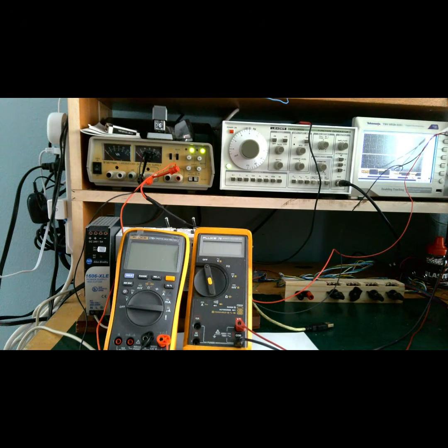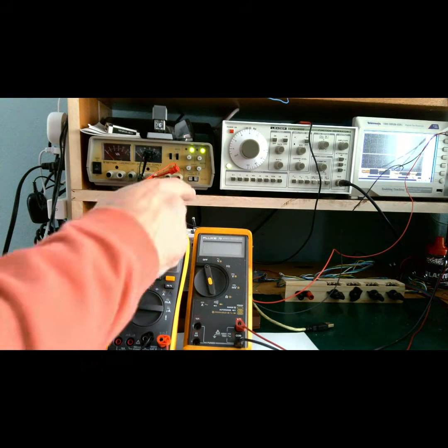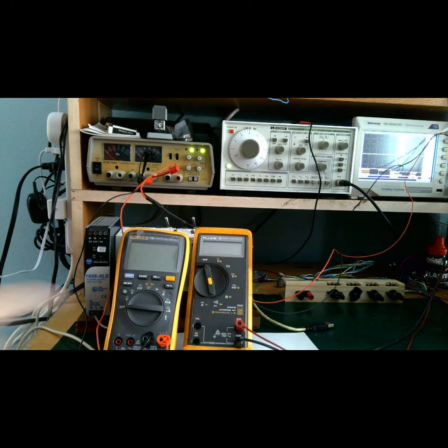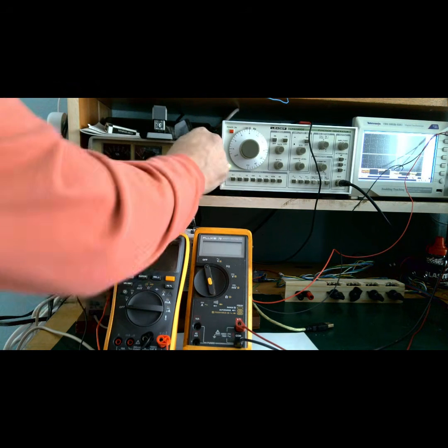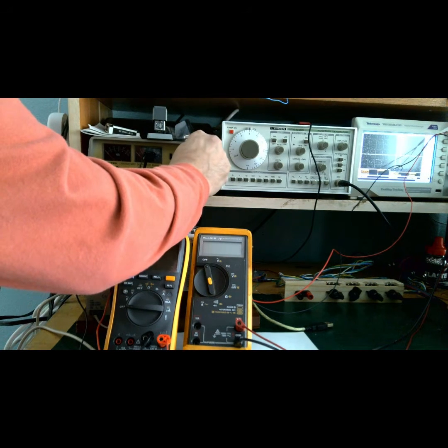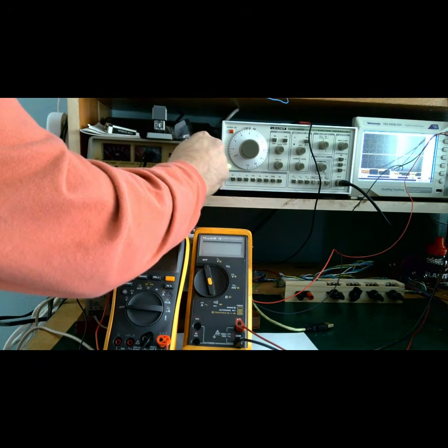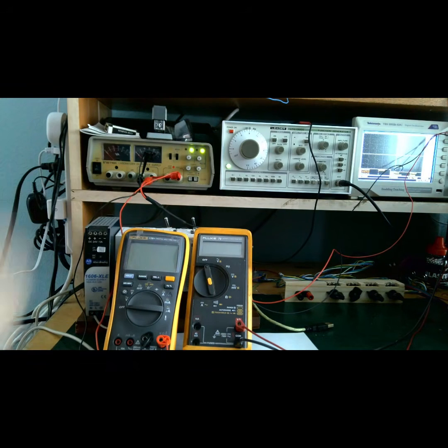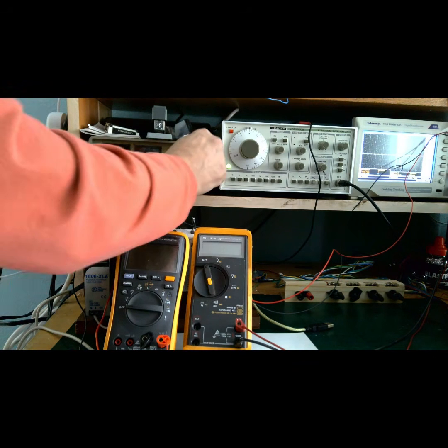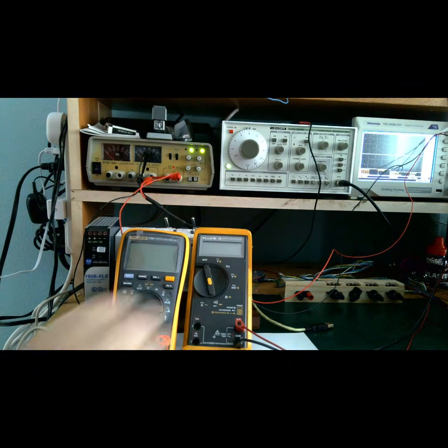All right, what I have here is a generator with an external input. If I put a DC voltage into that input, it will change the frequency coming out of the generator. So, for instance, if I turn the voltage up here, I think you can probably hear that coming through the camera. It's changing the frequency. So basically what we want to do is take a look at the different notes and the frequencies and figure out what DC voltage we can apply to get that particular note.